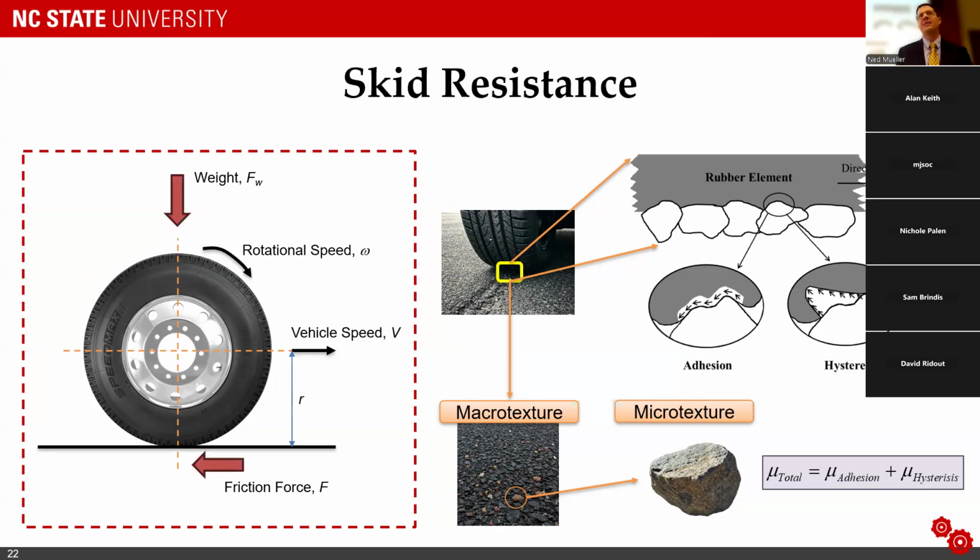A contributing factor to this surface friction is the amount of texture that we see on the asphalt concrete. Higher texture, especially what we refer to as macro texture, which is the texture that we see with our eyes. Think about wavelengths anywhere from 0.5 millimeter to about 20 to 50 millimeters, so around an inch or two. We see as macro texture, and that macro texture helps to do a lot of things. It helps to deform the tire as it's rolling. It also helps to collect water in wet conditions and increase the effectiveness of tires.